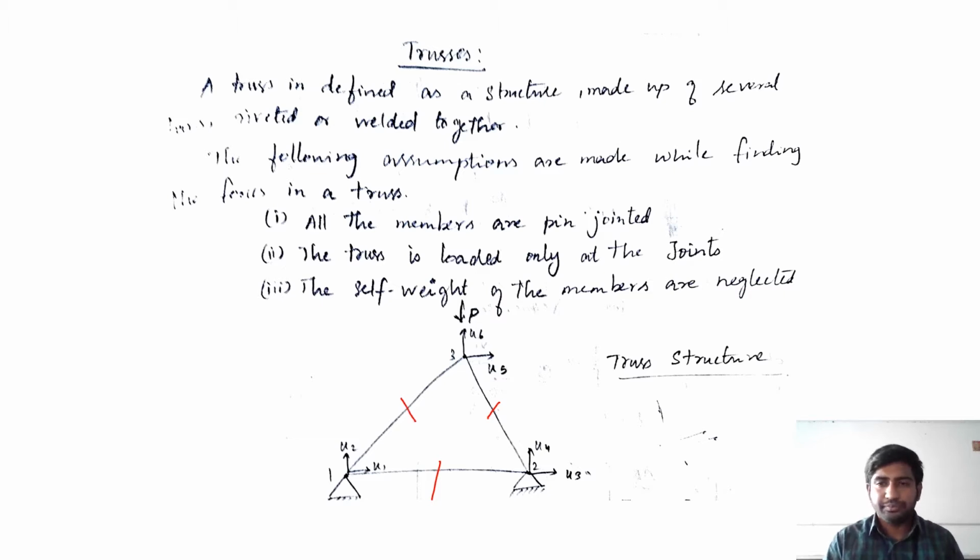Okay. So similarly here the joint is also called nodes. So the joint is known as nodes, as you know. So here this is first node, here this is second node and third node. Okay, node 1 and 2 are fully connected and there are no degrees of freedom here. The u1 and u2 are fully fixed, u3 and u4 are fully fixed. Here u5 and u6 are free, and the load is acting along lateral direction at node 3.